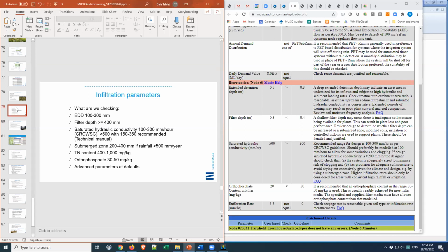Is it fenced off from the public? Is it isolated? In which case you start to have other issues of it becoming an eyesore and that sort of thing. So you need to think about, is this just an infiltration system in a nature strip or in someone's property, in which case you can't have that kind of depth, or is it a dedicated system in a park where you might accept higher depths?